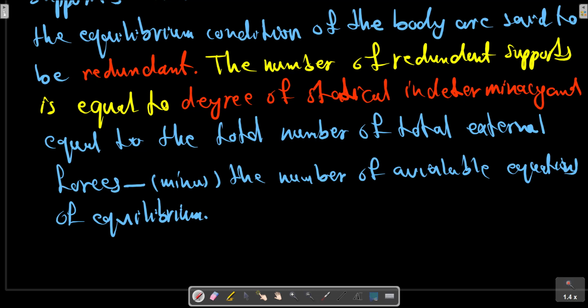We must be aware of the nature of constraints before we attempt to solve an equilibrium problem. A body can be recognized as statically indeterminate when there are more unknown external reactions than there are available independent equilibrium equations for the force systems involved.